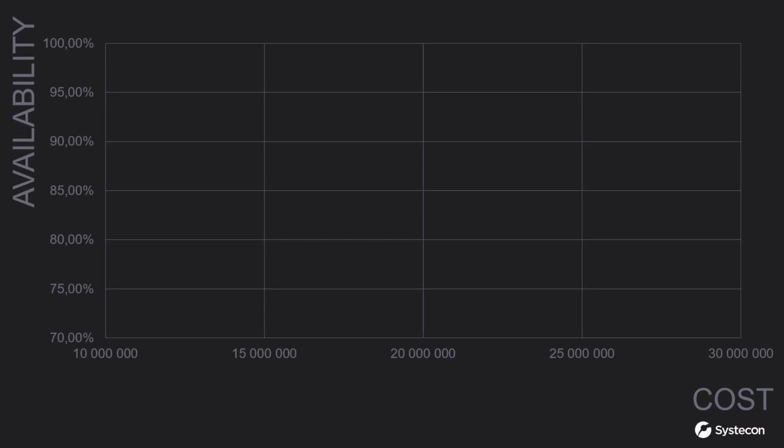To compare different solutions, we once again turn to a cost effectiveness type of illustration, and this time comparing system availability with associated costs. The blue dot here represents a spares suggestion produced with our previous method, where we were maximizing the fill rate. Given that method, the dot shows the cheapest way of achieving the requirement of 80% availability, meaning an average of 16 available helicopters. Now, if we instead shift the focus of the optimization from fill rate to availability, we may actually achieve our target for a substantially lower cost.